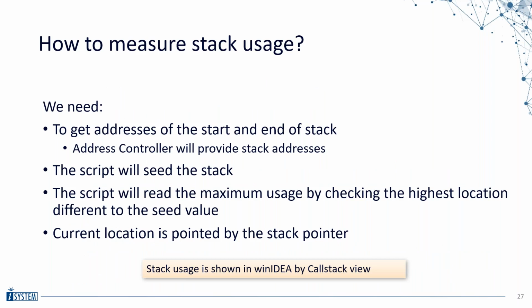The next use case will be the measuring of the stack usage. We need to figure out the addresses of the stack. What is the start, what is the end of the stack address. Then we can use a script to set the stack before startup with a special pattern, and then we can run the execution of the program.